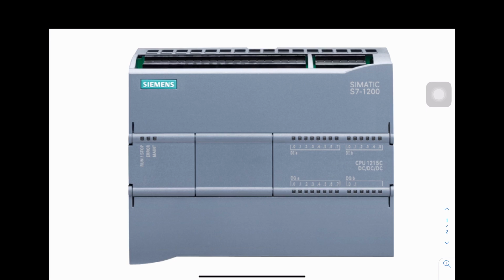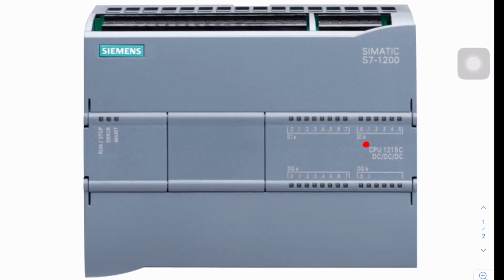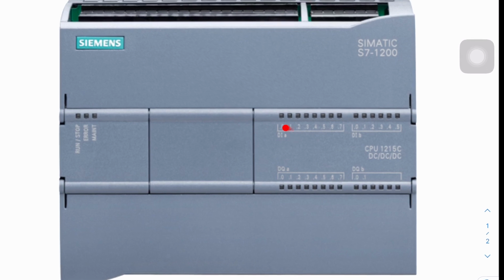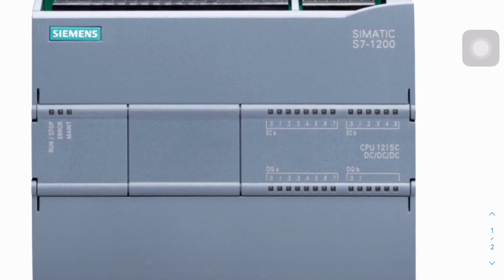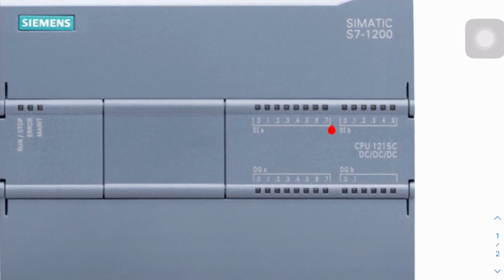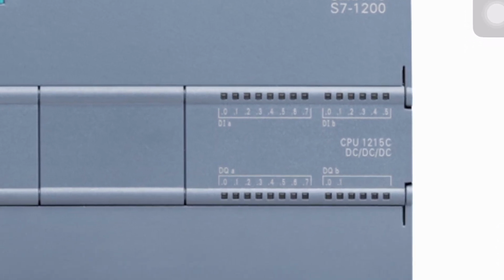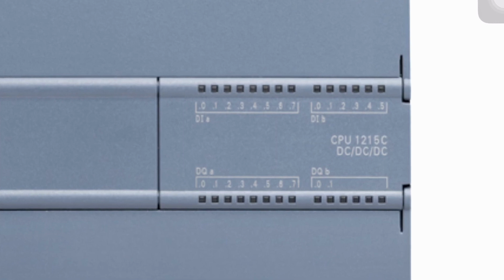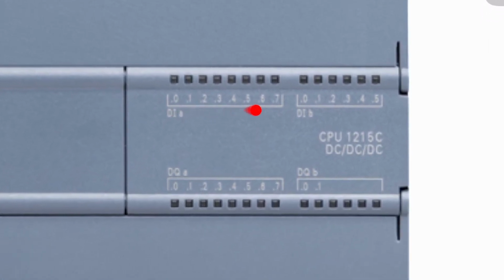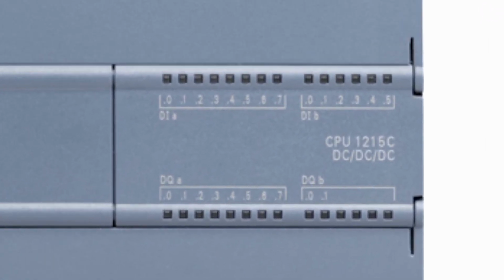Looking at this PLC, we have two digital input channels. The first one is digital input channel A, and the second is digital input channel B. For digital input channel A, we have 8 bits starting from bit 0 until bit 7. For channel B, we have 6 bits, which is from bit 0 until bit 5.